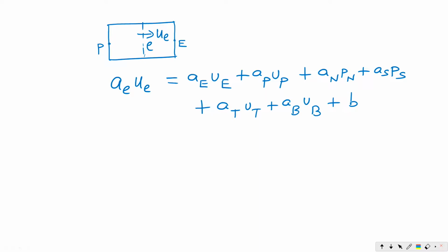Along with the source term, there is one more term called what? Minus dou p by dou x is also there, that we will discuss and substitute over here. I have to add one more term for the pressure gradient. So this is a generalized form of the discretized form, using the finite volume method, for the u momentum equation, because it reflects a part of the convection diffusion equation.